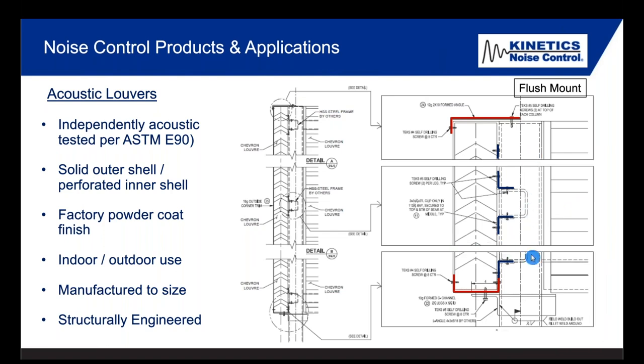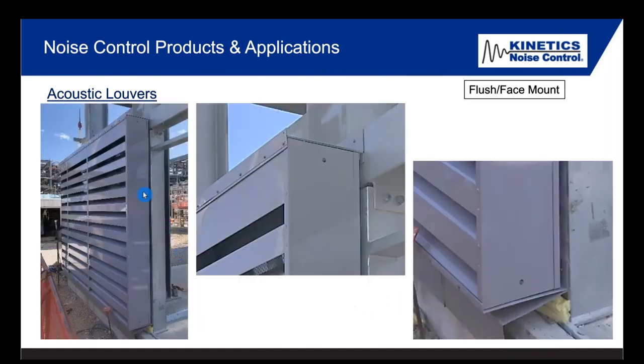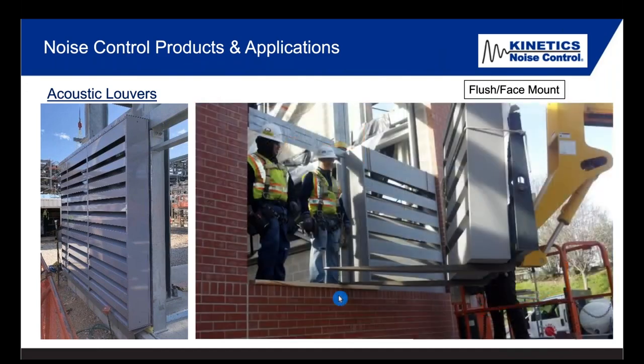Mounting louvers to third-party steel instead of the barrier wall system, you can mount louvers to that. This is an example here. You see the steel behind it. You see this top system, and I actually put in there so you can see that better. The bottom attachment here is a continuous channel, and that's all engineered to be the proper gauge and proper structural strength to meet the local IBC wind, pullouts, and uplift. And then here, always happy contractors installing, but really seriously, it's nice to show how the louvers can be mounted in with backing steel. Sometimes the backing steel is needed and sometimes it's not.